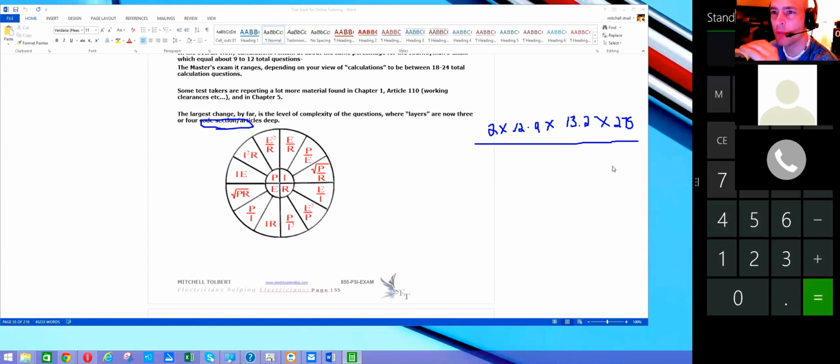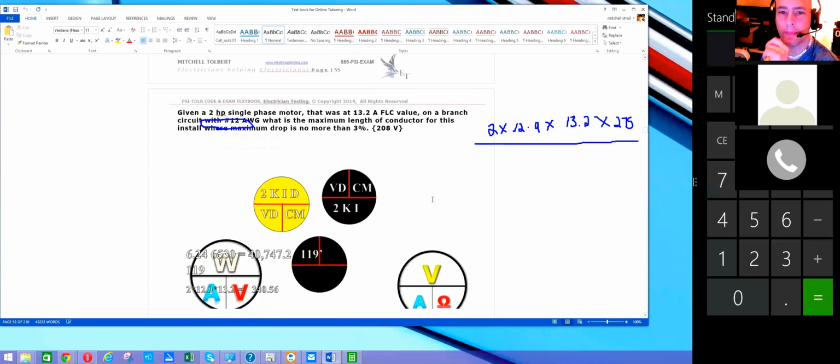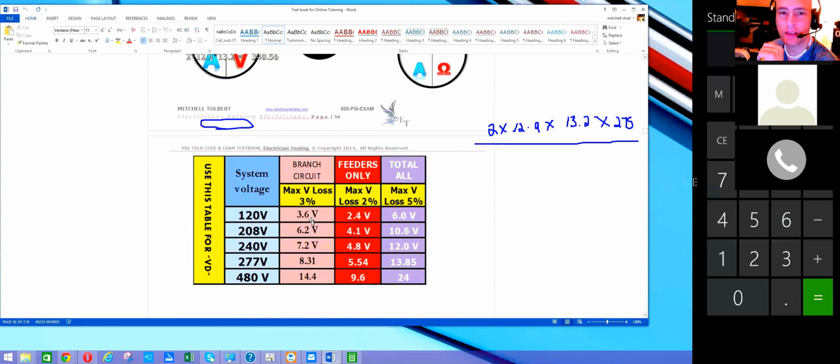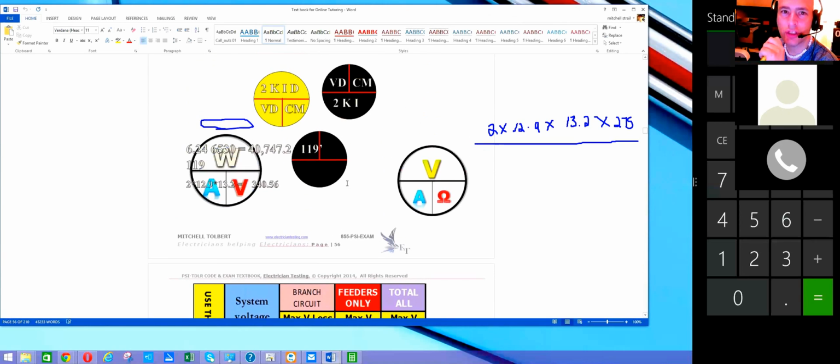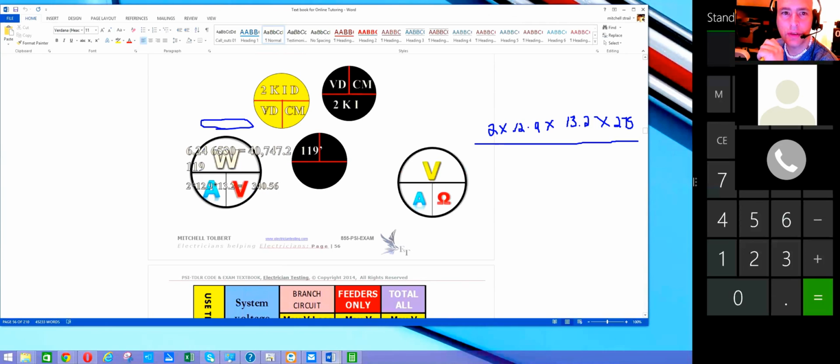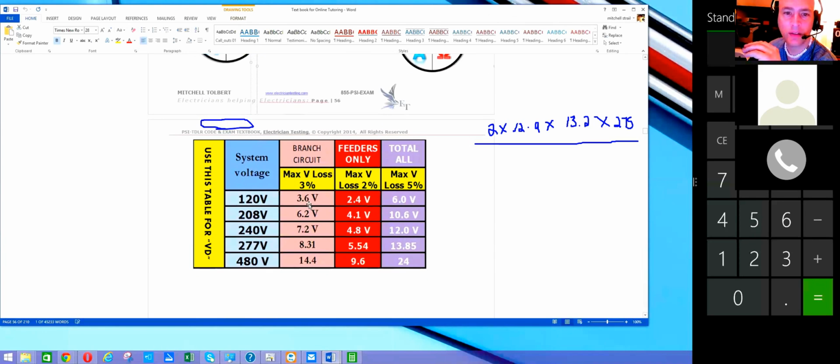So you had the top number based on 25.8 times 13.2 times 275 feet, right? Correct. So 93,654, and then you just didn't know what to do with this number. Exactly. I was stumped right there. And I knew there was something I needed to divide by. This little table right here is why I did this little table. If you're looking at this little yellow circle, we have to solve for a bottom variable. In this case, we're looking for wire size. So it's going to be these numbers, which is what this 93,654 represents, and then this voltage drop right here. Anytime I have to use this in the formula, I come down to this table and pull the value off this little chart. There you go.